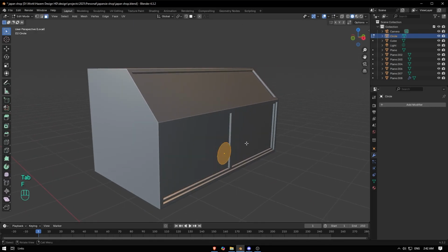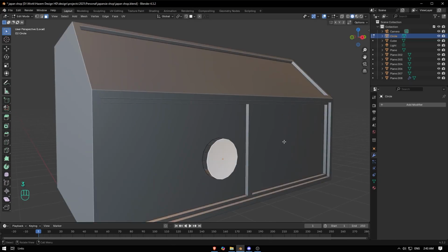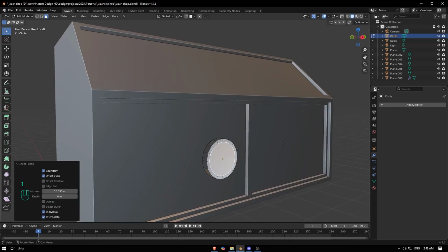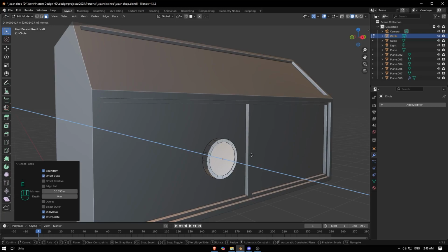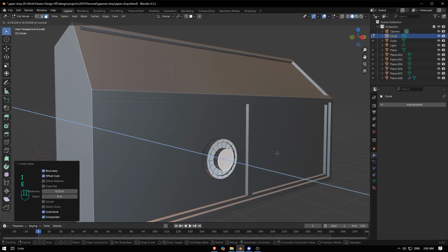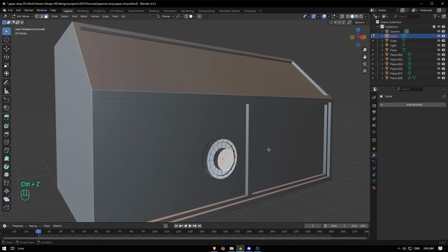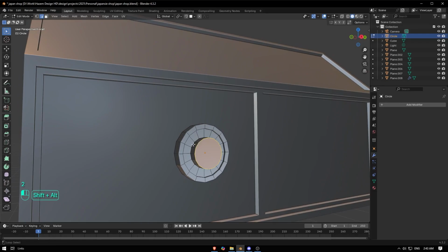F to fill in edit mode, and then E for extrude. Then go select this face, hit I to insert face, extrude inside, and then I to insert face again, extrude like this, and maybe scale down, or I don't know, but feels this one is good.